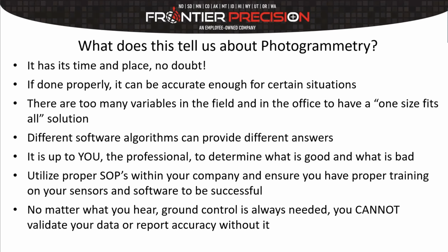Okay, you hear that a lot, survey grade this, survey grade that, no ground control this, no ground control that. You cannot validate your data if you don't have any checkpoints or any ground control to report your accuracy to. So always have something on the ground to validate your data every time you do this.